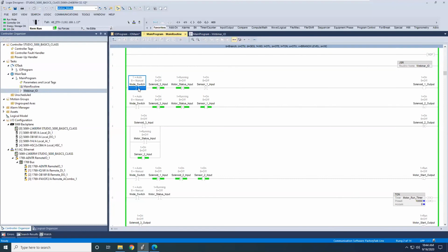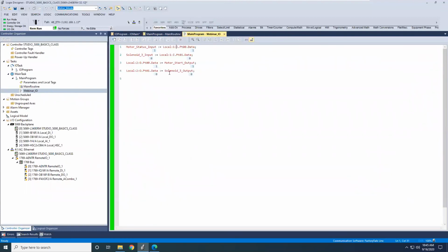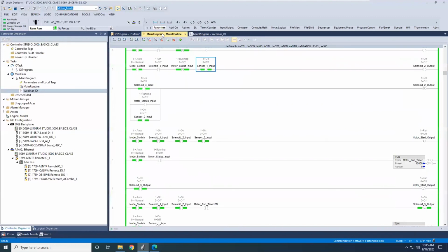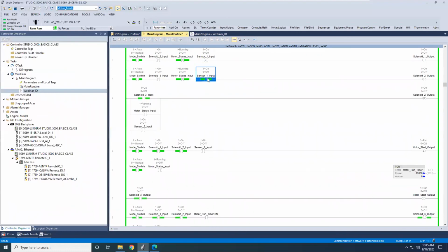One more thing I wanted to point out, because we haven't gone through this yet. Our motor is running, so you can see the live inputs transition there. Previously, this is all you would see. You just hope everything is working. Now you can add these little glasses. Those didn't exist until version 31, so that's a key feature you definitely want to use if you have it. All right, so I'm going to hit Control Z and turn everything back off.